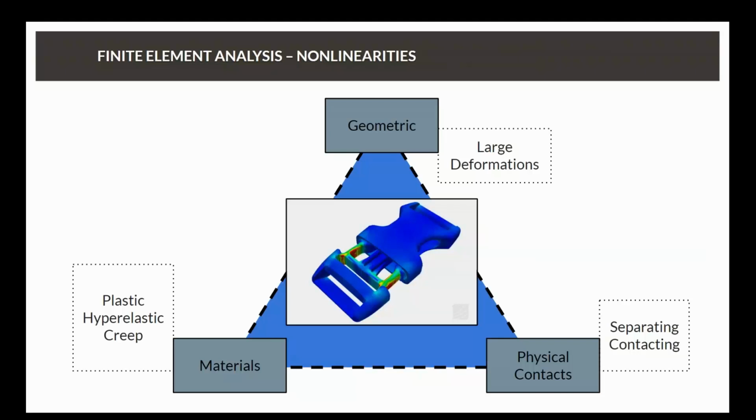So a little bit more on non-linearities and what we can really offer in the platform. A bit of background. If we're talking about statics, a linear simulation is one in which the stiffness matrix remains constant through the full length of a simulation. Now, for a non-linear type simulation, that stiffness matrix is actually going to change as the simulation progresses.